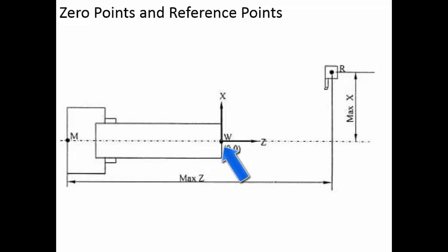We will bring the tool or some dial indicator and touch the end surface of the workpiece. Whatever the readings are in the CNC, whatever the x value is and whatever the z value is, that will be the origin. That is how we give the input to the controller. So the controller will remember that okay, x minus 345 or x minus 271, this will be the origin.